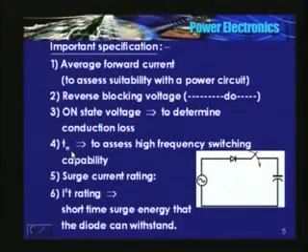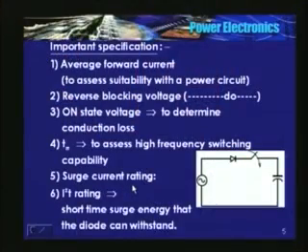The fourth one, trr, reverse recovery time of the diode, is another very important factor in the diode used in high switching applications, or it is required to assess the high frequency switching capability. And the fifth one, the surge current rating.